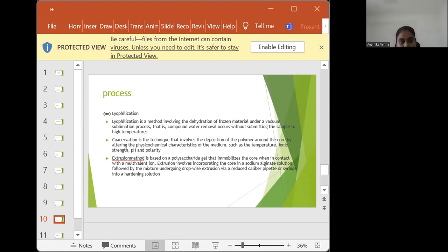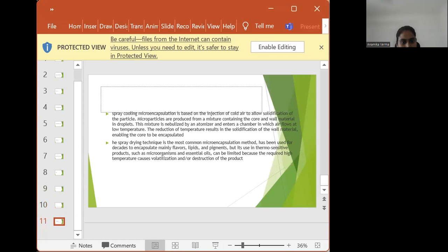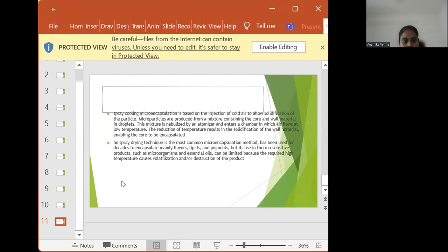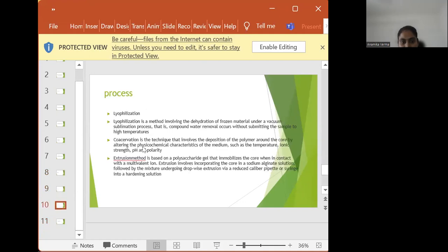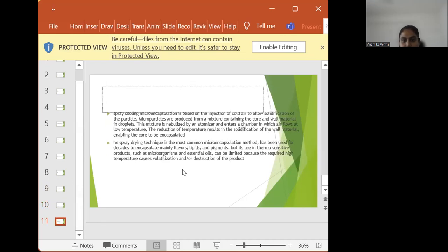Solid particles to be encapsulated are suspended on a jet of air and afterward are covered by a spray of liquid coating. The process of suspending, spraying, and cooling is repeated until the attainment of the desired coating thickness. Now, the spray drying and the spray congealing.